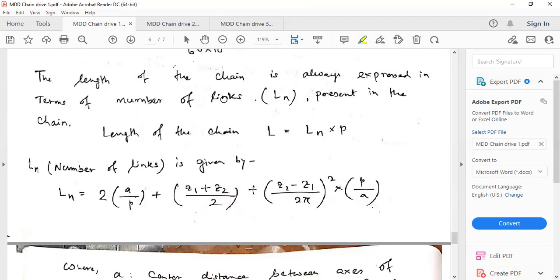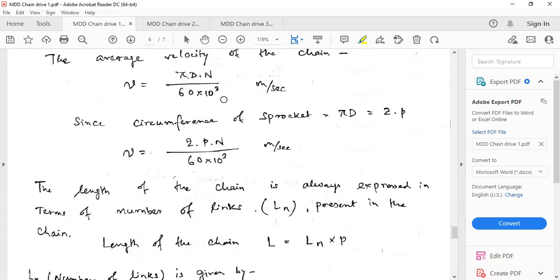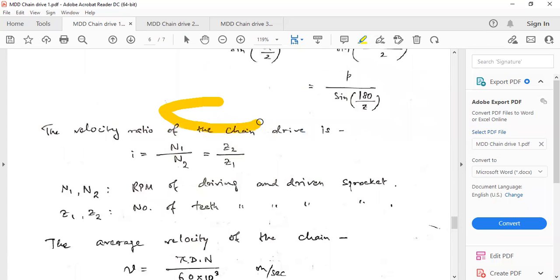If you add that link, it changes the strength and all these ratings. So what you have to do is add a link to make the total number of links even. That's fine, but you cannot add one extra roller to that, because the other side will remain open, isn't it? So what you do is overlap one link with another one.